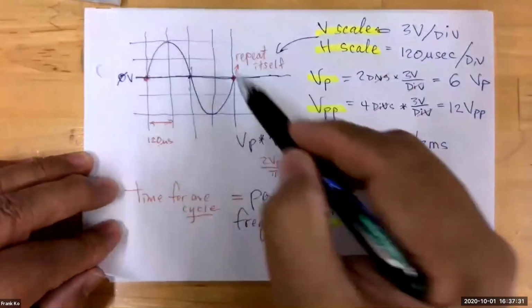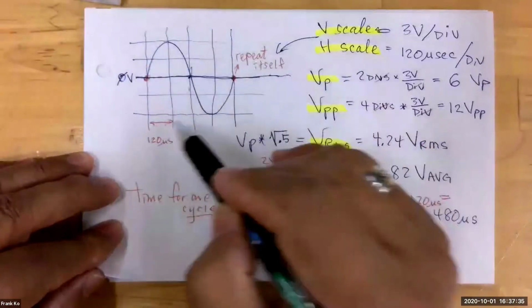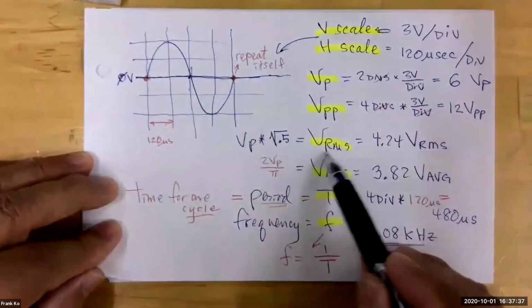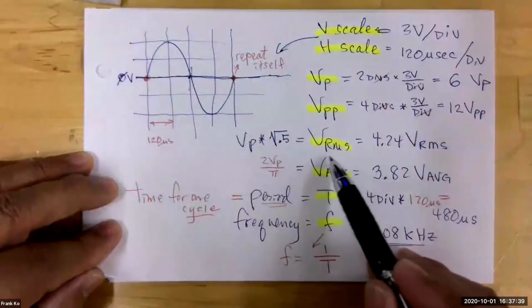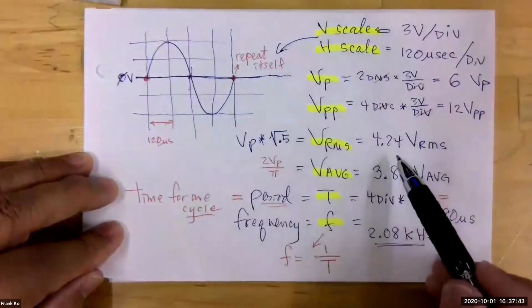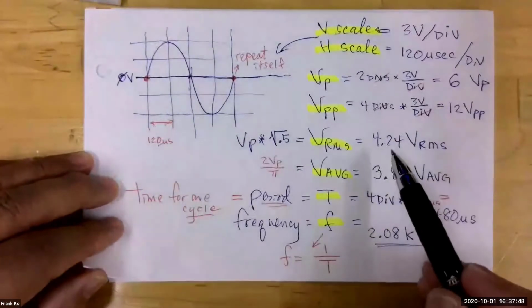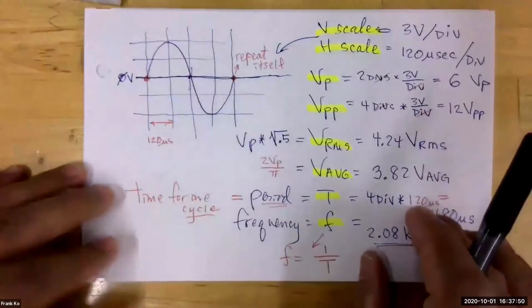Your multimeter can only give you a singular digital value, and that would be the RMS version of that waveform, which we should be able to verify as 4.24 VRMS for our source. We're going to do that next week because you're going to build this circuit.